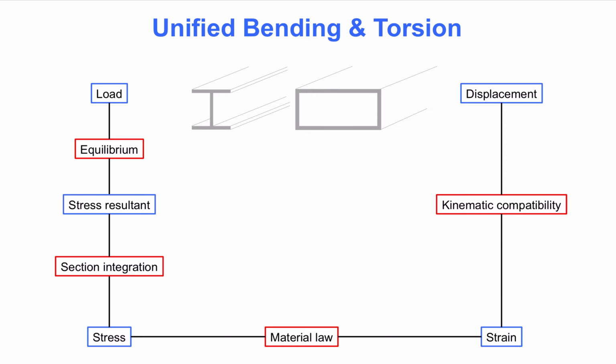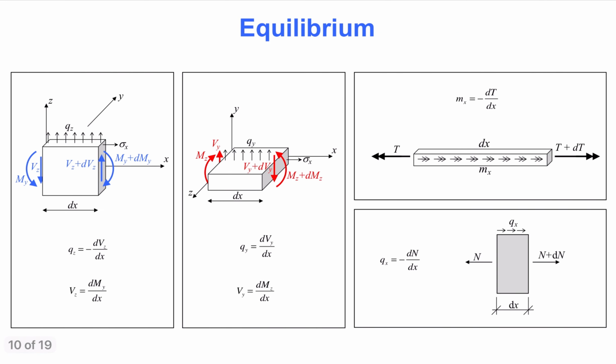It is possible to include shear deformation, as is done in Timoshenko beam theory. That is done in the document on warping torsion posted at terje.civil.ubc.ca, Toolbox, but it is not included in this video. The next slide shows equilibrium equations that match exactly those derived in the videos on truss members, Euler-Bernoulli beams,